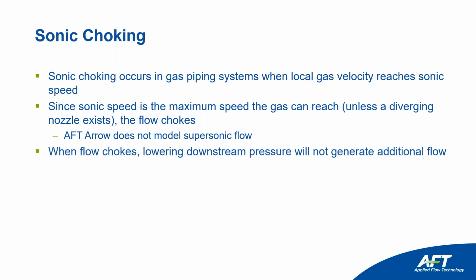Okay, so this was the bullet point that I was talking about, where if you were discharging into a downstream pressurized tank, lowering the downstream pressure will not generate any additional flow when the flow has choked. So that would be unfortunate if you're trying to get additional flow.